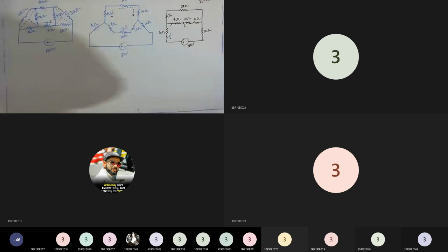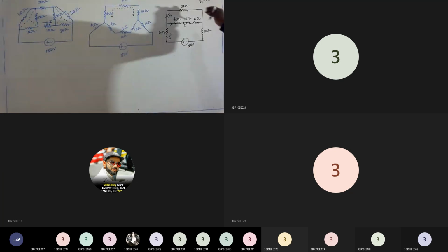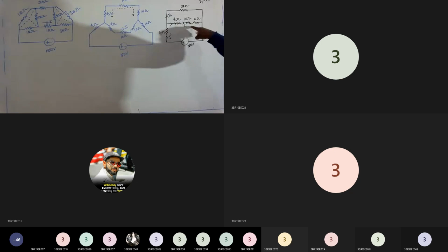In order to find out the total current of the circuit, first we should know the total resistance of the circuit. Let us simplify. Now 38 ohms and the series combination of all these three are in parallel, correct? So 24 ohms and 38 ohms are in parallel.